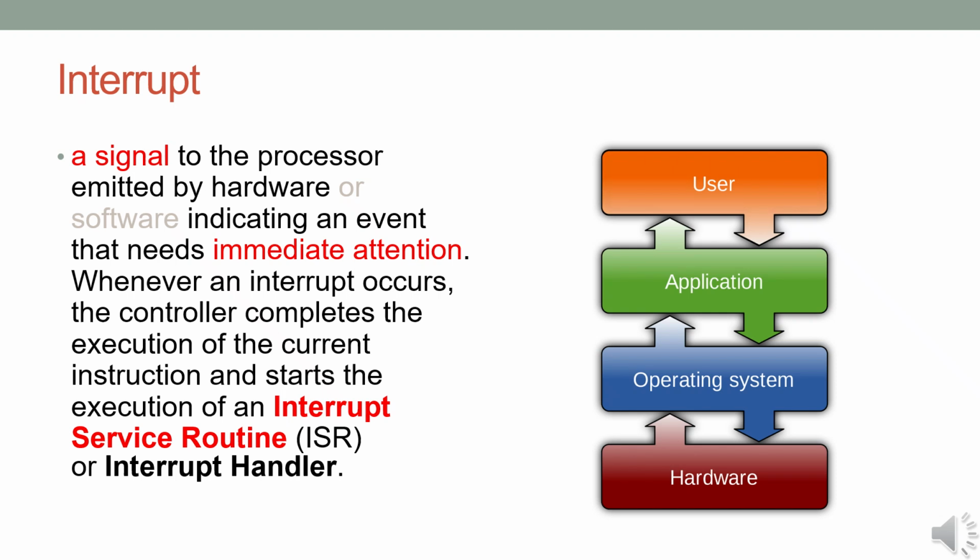This setup is much more efficient than polling, which would require the system to constantly monitor the button's status. Efficiency in GPIO management. Using interrupts helps make GPIO management significantly more efficient. Instead of wasting resources constantly checking pin status, the system can focus on its primary tasks and only respond when necessary.